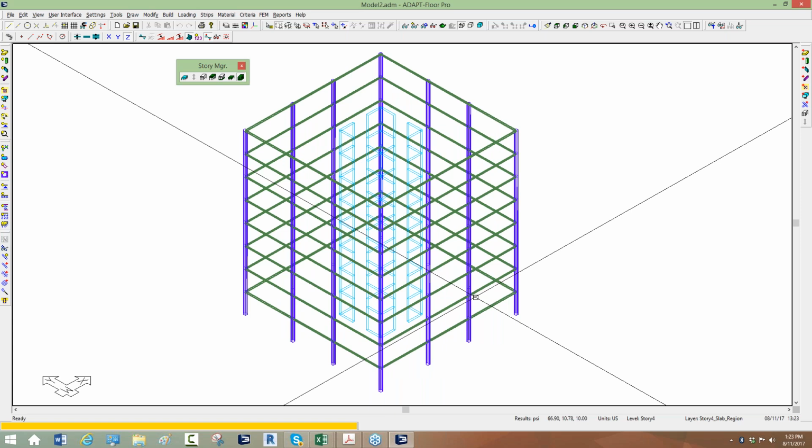So we're going to switch gears now, and in the model, the program imported gravity loads. What we want to do is make a comparison between the imported reactions due to gravity, let's just say dead load and live load, from the finite element analysis in Etabs, and compare that with a tributary load takedown tool within Builder.